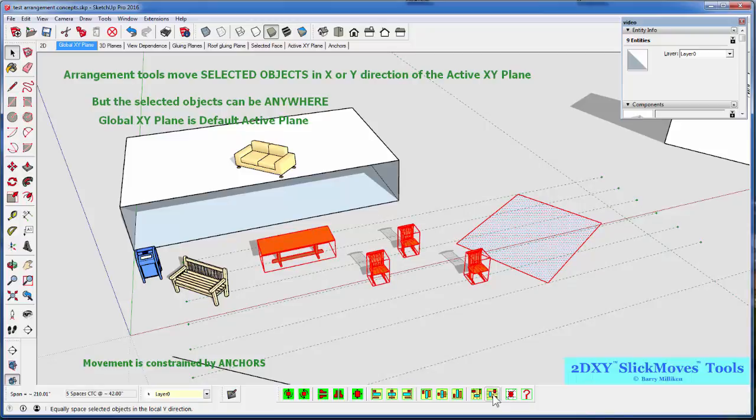So you see you have a rich set of options in selecting objects and the different kinds of anchor points, either the outside objects themselves, sometimes a double anchor object if it's larger and spans the entire selection, and any number of edges selected to define the overall extent, minimum and maximum X and Y.